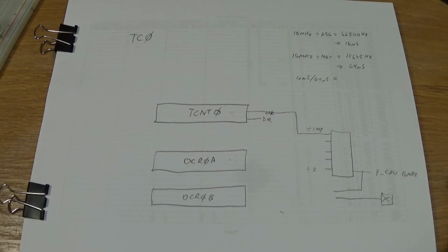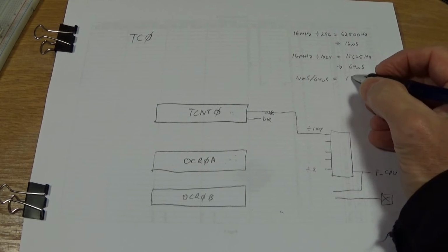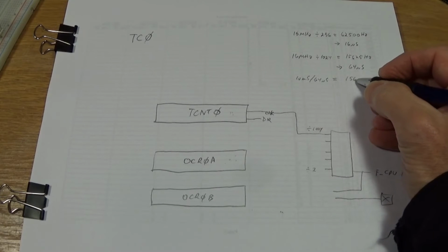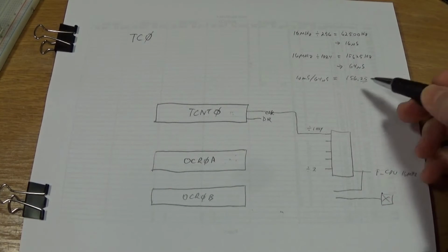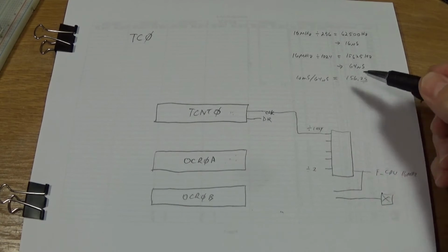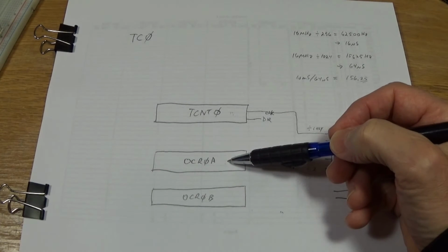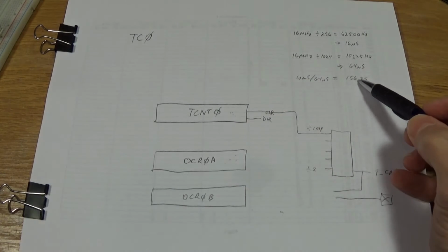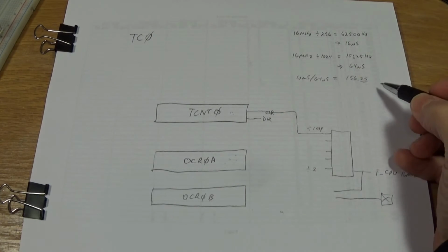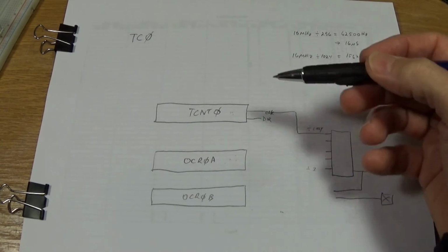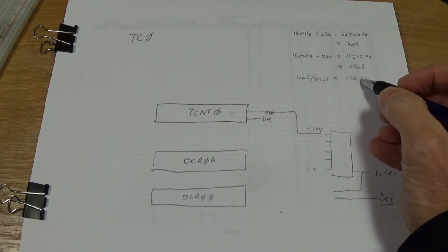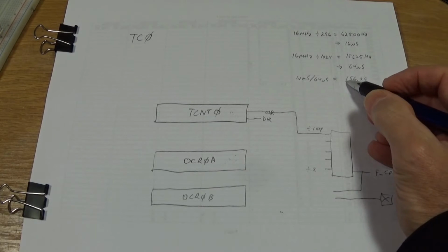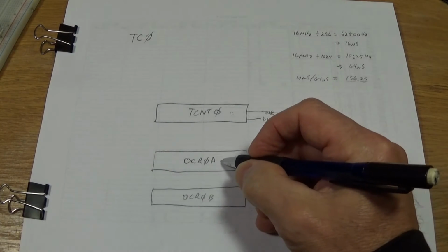and divide. So I get a value of 156.25. So there's a bit of an error there. So I need 156 counts into this register here in order to give me, actually it's 155 counts because you have to take away one for the rollover. But so I put that number here, not the decimal because I can't get it in there, but I put 155 into this register here,